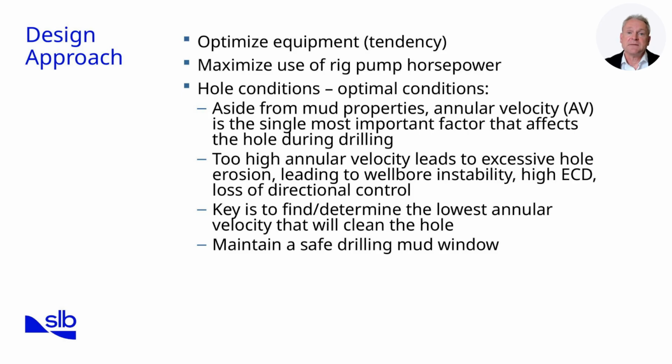The third point emphasizes hole conditions. Apart from mud properties and inclination, annular velocity is the single most crucial factor for hole cleaning. However, too high an annular velocity can erode the borehole wall, leading to instability, higher ECD, and even loss of directional control. The key is to determine the lowest annular velocity that will still clean the hole.